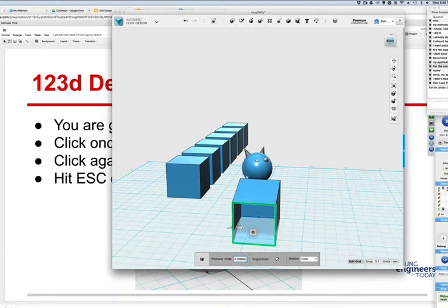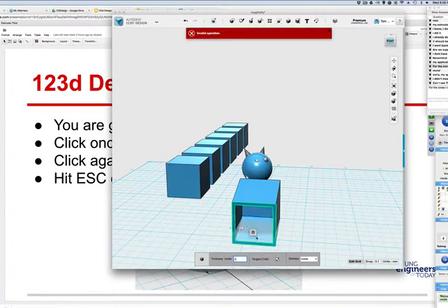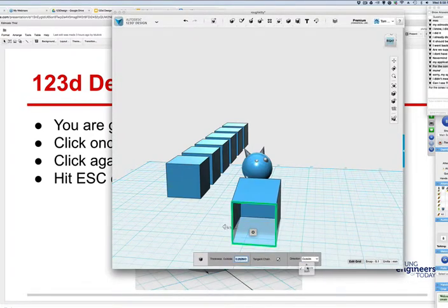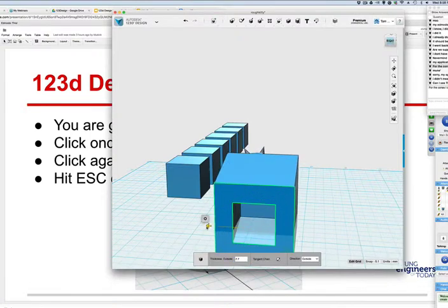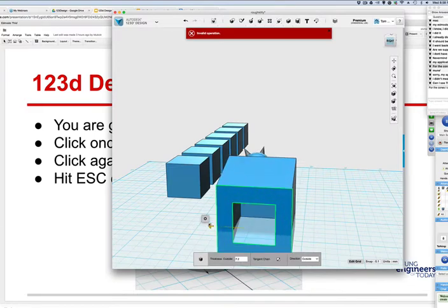So this is really useful if you 3D print something, and the depth of that, how thick you want to make this, you can say, I want the thickness and size to be such and such. So watch if we make the thickness 0.1. That wall is much thicker. All right? And you can do things like, here it is, outside. So we're taking it on the outside, and we can pull it out like this. See that? How cool is that?